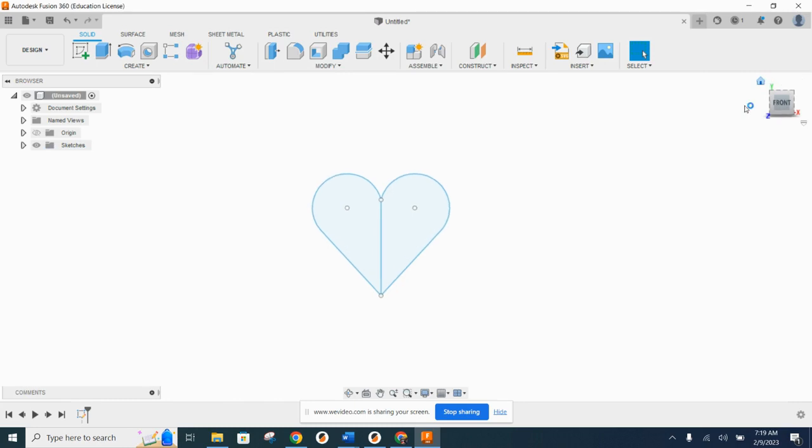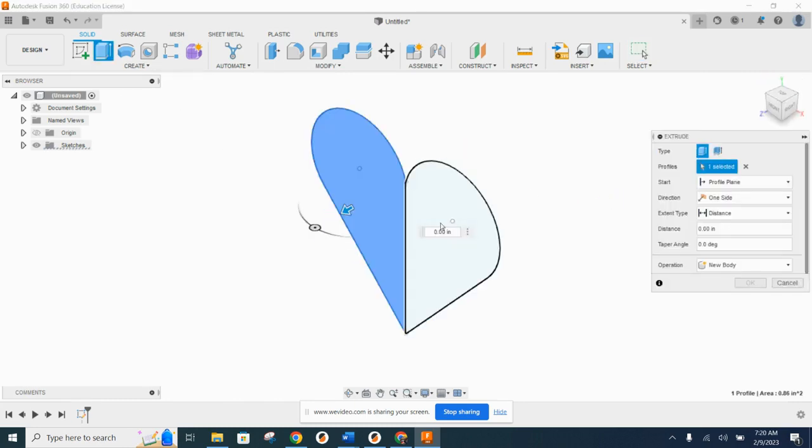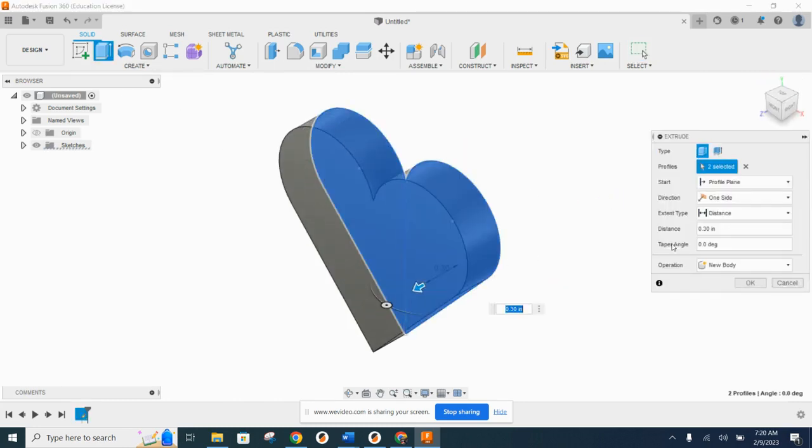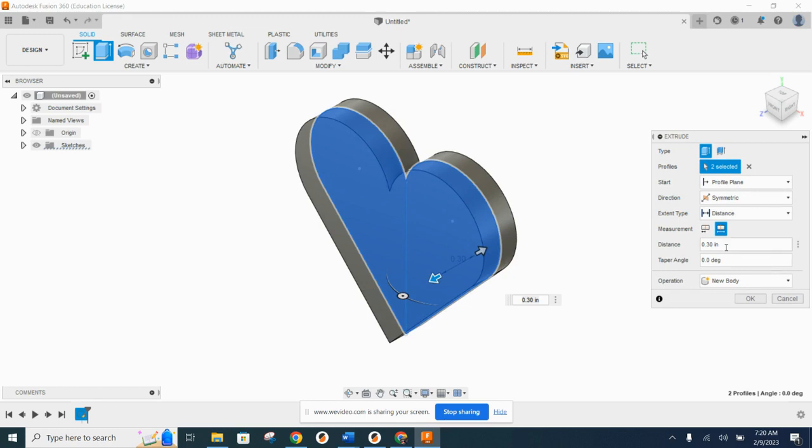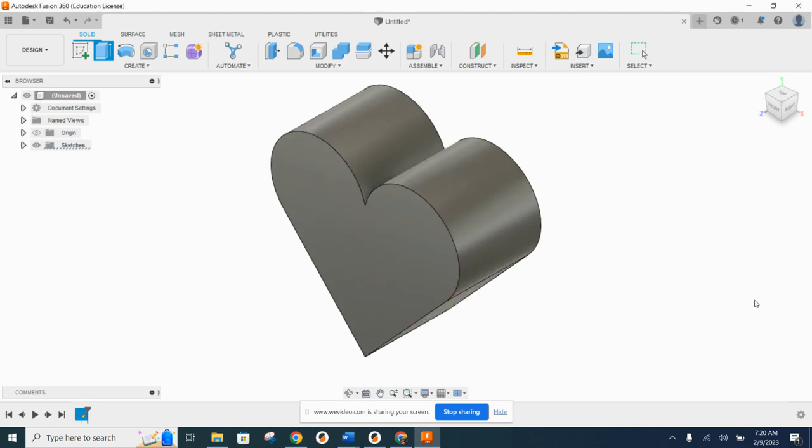Okay, and now I can go ahead and finish the sketch up and I can do an extrusion of this heart. What I'm going to do is keep this symmetrical because I do want to use that origin later. I'm going to say that my distance on this is 3/4 of an inch for my extrusion. Now we can go ahead and start making the shape of our heart.